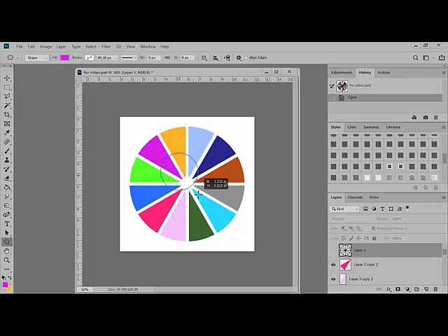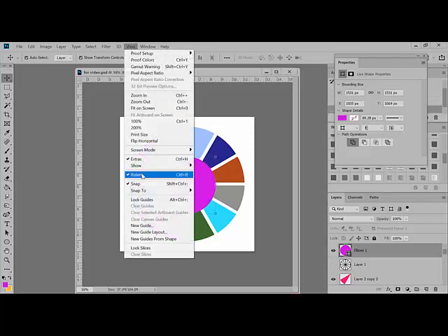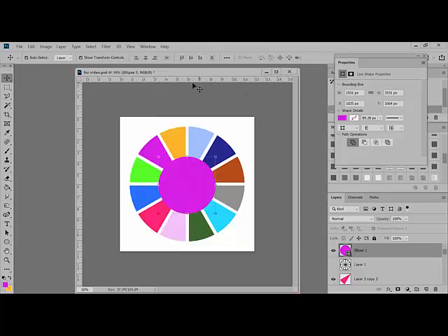When you click and drag, if your circle is becoming distorted, you'll know that you need to hold down the Shift key as you click and drag. It's different in different versions of the software, so just know that if it becomes distorted and you get that weird funhouse effect, you need to go ahead and hold the Shift key. Center the circle on the triangle. You can use the rulers if you need to get it centered. Just select View, Rulers from the menu bar, and then using the rulers here, it will help you to be able to find the center.